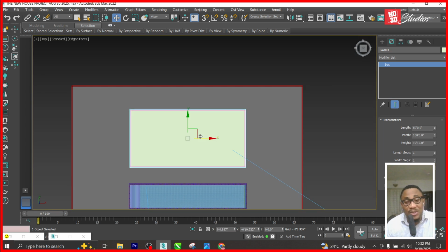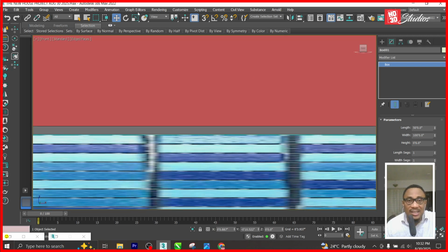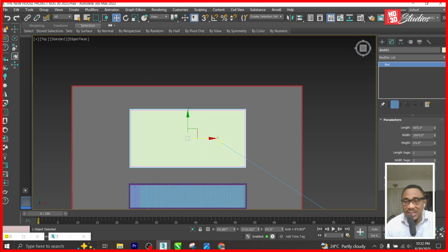So I'm going to convert this into the slab. Instead of the height of 20 that you have here, I'm going to do 0.5 of a foot. Good. Top view. Let me reduce the width and height a bit so that they will not show out there. So this 50, let's make it 49.5, then the 100, let's do 99.5.